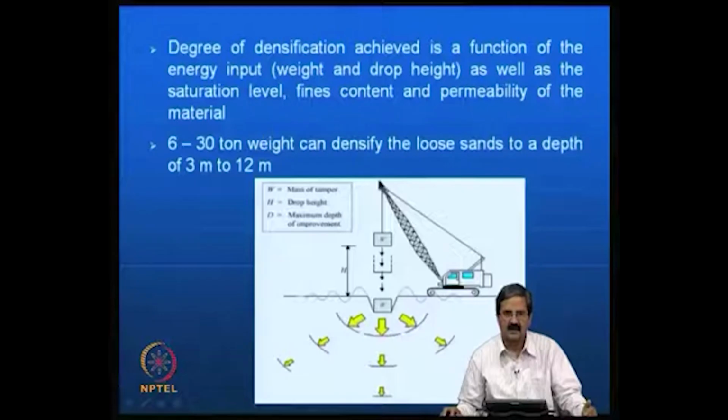Then these weights of 6 to 30 tons can densify the loose sands up to a depth of about 3 to 12 meters. So, for example, if the depth of compaction that you need is about 12 meters, then one can use this technique.